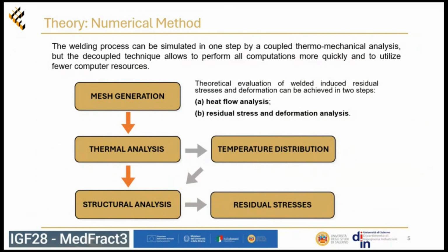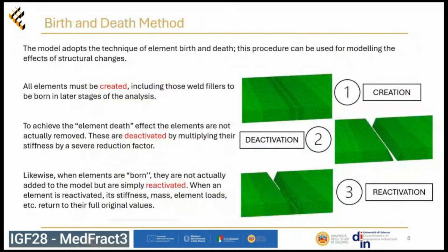First of all, we created the model with the mesh. After that, we performed the thermal analysis to obtain the temperature distribution, which we converted into thermal load and used as input for the structural analysis to obtain the residual stresses.